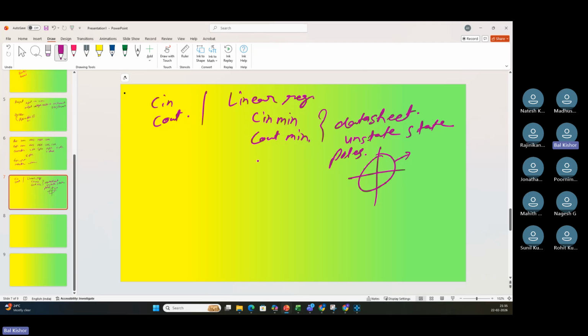Okay. One more thing that they generally give, let's say if you follow ROHM Semiconductor, they give you the C in maximum and C out maximum. Like what is the maximum capacitance that you can use, not more than that. So those values are generally up to 1000 microfarad or something. Sometimes Texas Instruments also mention their capacitance requirement that will be around 100 microfarad or something for lower grade, very low power application. Okay.